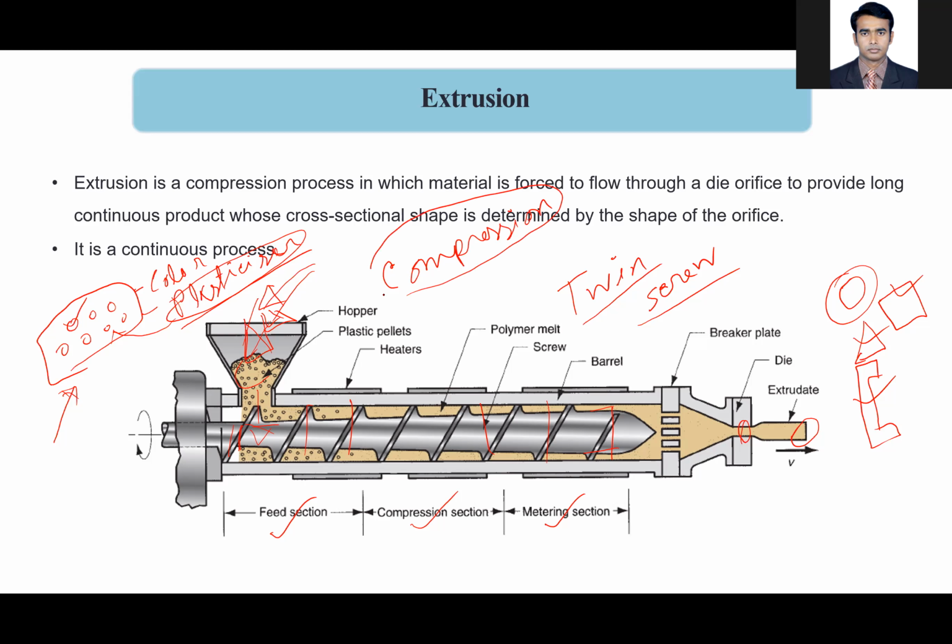Pressure, compression, it's kind of similar. Okay, the main thing here is the main problem. If we do not use this compression, that means the gradually increasing diameter of the screw, what will happen is that there will be a lot of pores, because we are using particles here. The particles contain interparticle gaps, and that contains air, right? And if we do not compress it, then there is no chance that these air gaps are getting out.